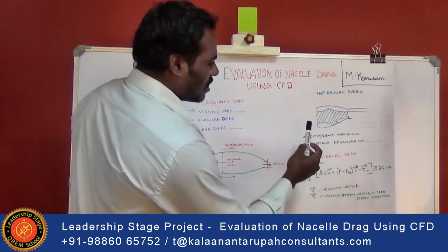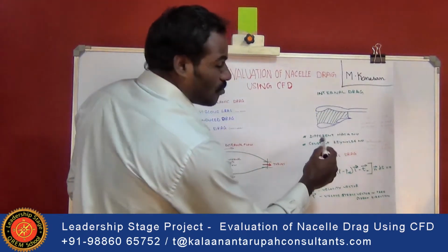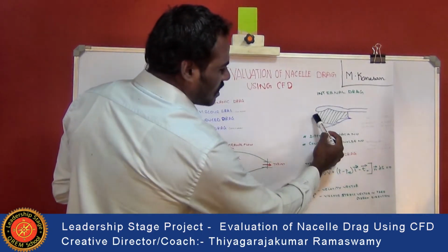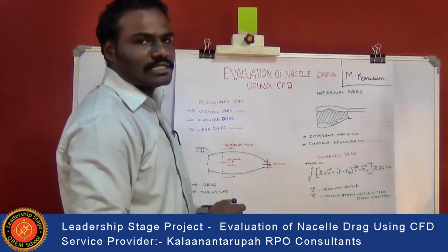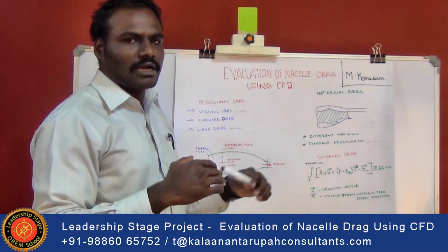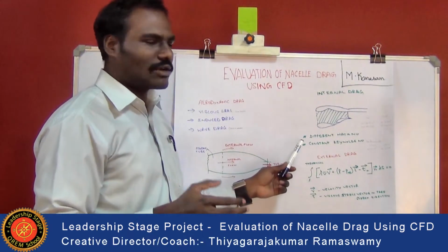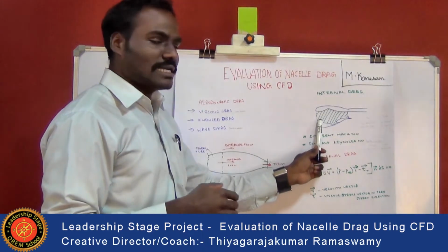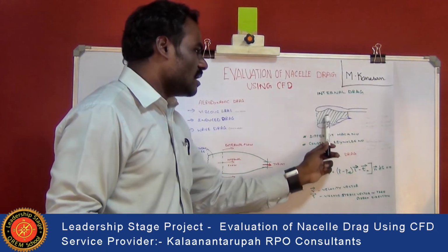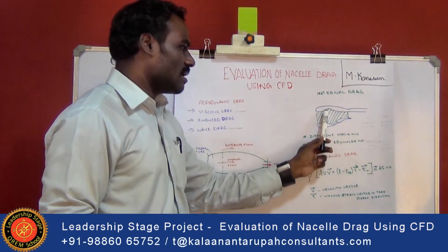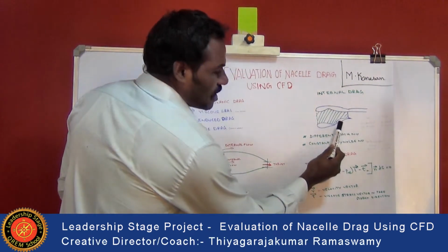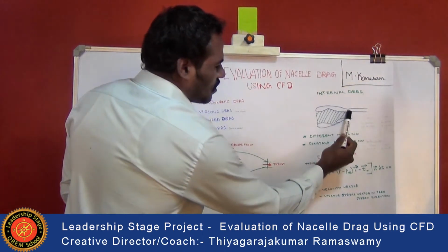At the conclusion, we are just finding out where more drag is carried out, and at what region the drag is carried out at the interior region, and at what areas the drag is more when compared to the other two methods, where we calculated the exterior drag, as well as the inside drag. When the airflow is inside, it is subjected to a split in the airflow. Most of the split is carried out at this region before entering into the exhaust of the nacelle structure.